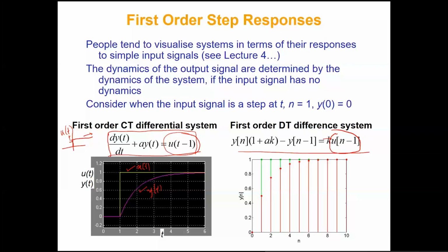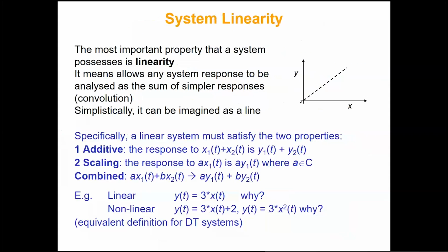So we can give a shifted version of the step signal or a scaled shifted version of the step signal. Here you can see it has a scaling factor of k. So that k can be 1, 2, 3, 4, whatever value you want to give it. And u of n minus 1 is basically just your step signal shifted right by 1 time unit. So we can give that input and see what the output is. In this particular case, the green lines that you see are the input, and the red lines are the output y. So these types of things we can just do in MATLAB.